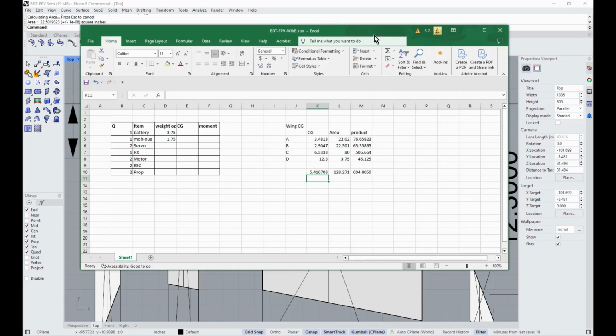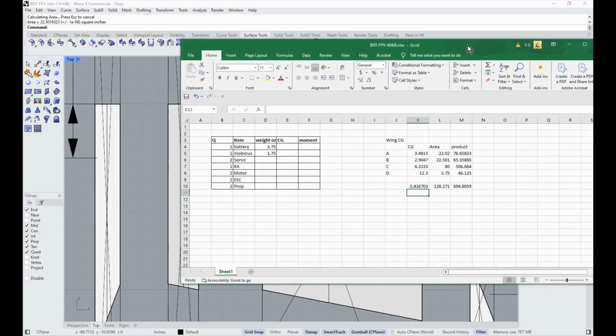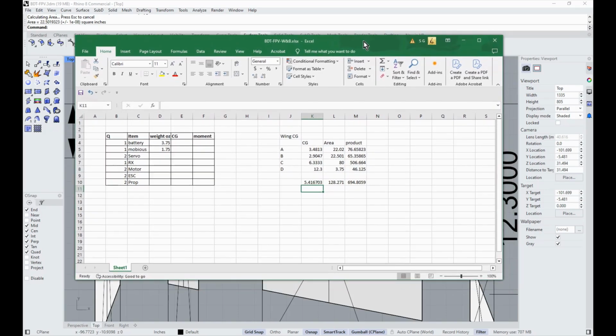Of course, if you're just doing one section, you just stop there and you'd have your mean aerodynamic chord, you know where in space the 25% line is, all that. But this is getting into how you compute this for a complex shape as shown here.